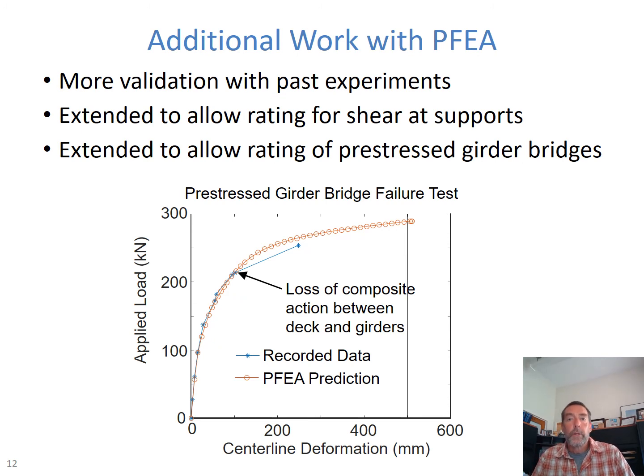We have done some additional work with PFEA. We've validated with additional experiments conducted by others. We've extended it to allow the rating for shear at the supports, which can also be an issue with these older concrete structures. It's also been extended to allow the load rating of pre-stressed girder bridges.